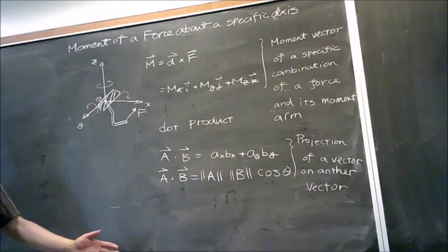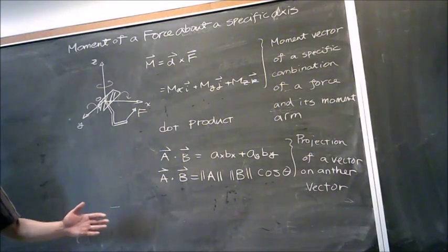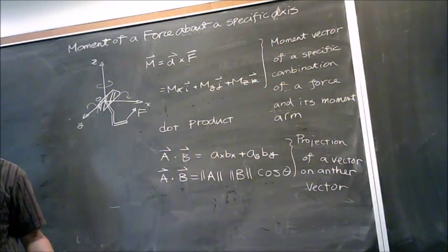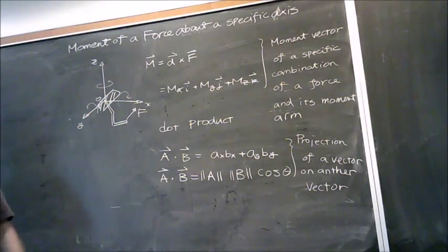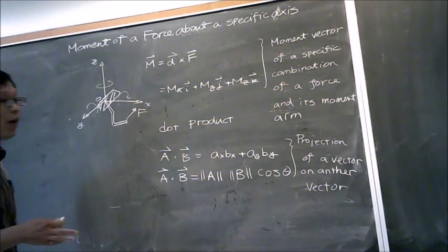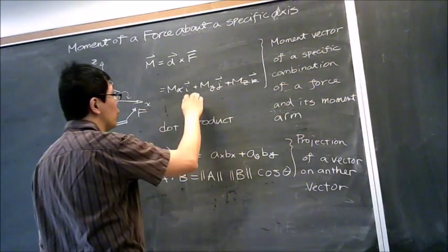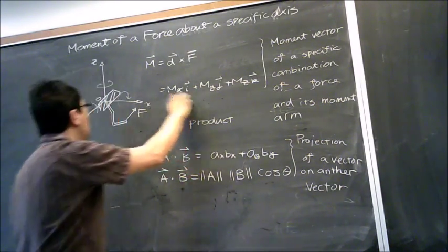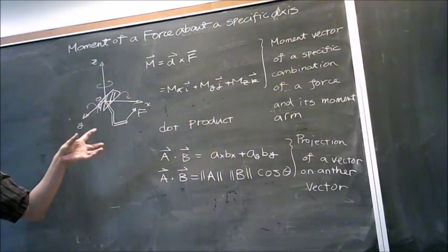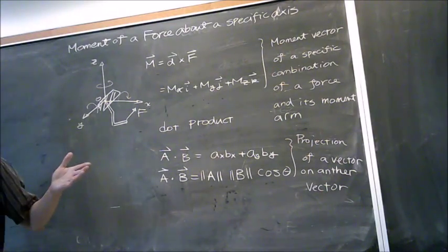So the moment about the fixed coordinate doesn't really make sense, because if you change your garage, the coordinate is going to change, but the relative position in your car may be fixed. So when we are doing that, what do I need to do? I need to find a way to project this force, this moment, along a specific direction or specific component in your car. Then you really know how much force or moment is actually created along that direction. Does that make sense to everybody?